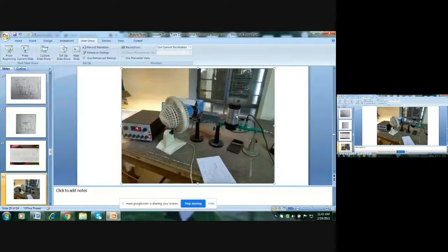If we change or rotate the frequency meter, then frequency of this cavity changes due to change in volume of the cavity. At a certain frequency, the frequency of this cavity is equal to the frequency of the microwave which is traveling from Klystron to the detector. At this point, the maximum power is absorbed by this cavity. Suppose 1 milliwatt power is propagating from left to right. We are getting 100 division deflection.